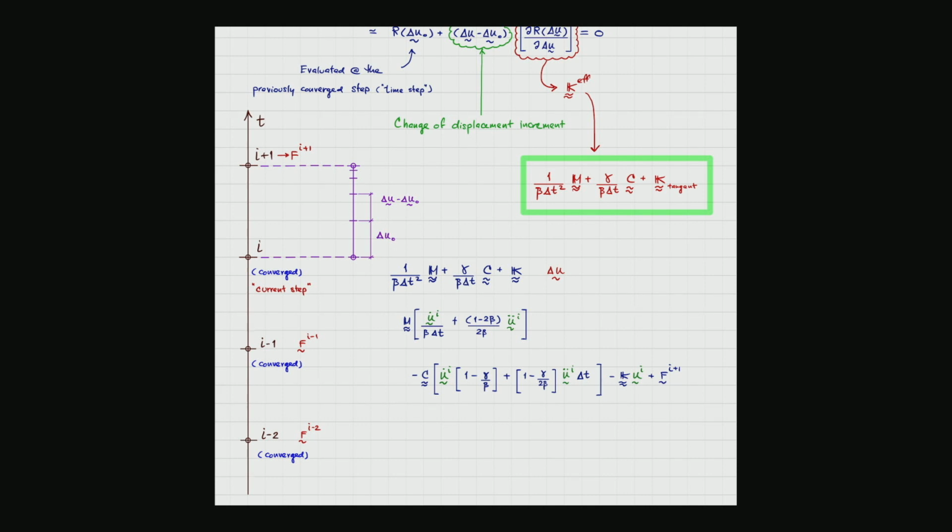The thing is that the step shouldn't be too big. When the step is very large, then the convergence of the nonlinear problem is going to be the issue. It might be more difficult for the code to get the convergence, and you do not want to have too many iterations in order to converge.